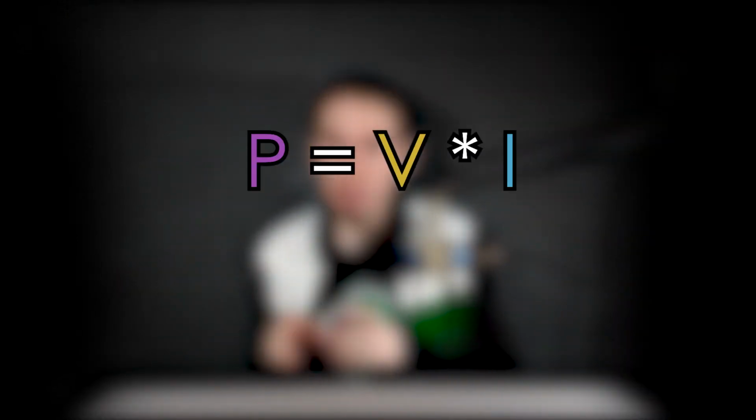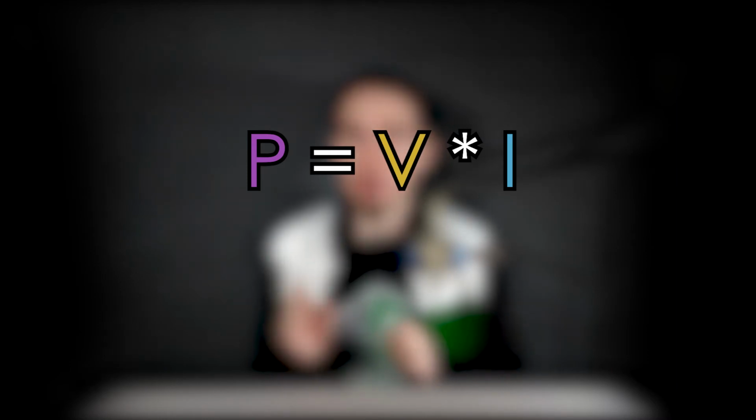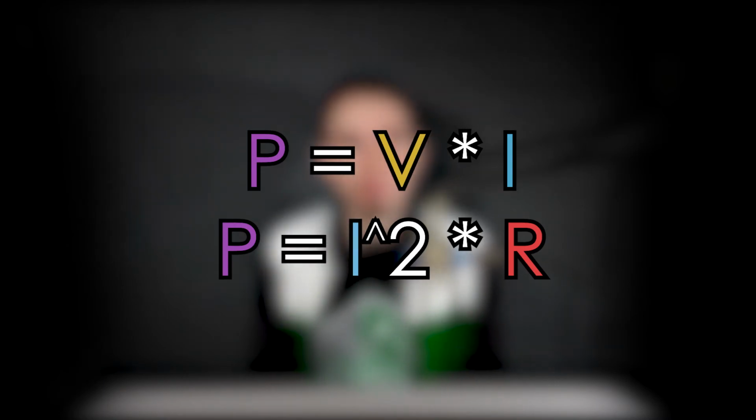Now, you can determine how much power is generated based off of the following equations. Power in a specific part is equal to the voltage across that part times the current going through that part. The other equation is power is equal to the current squared times the resistance. Let's do another example to see exactly how power works.